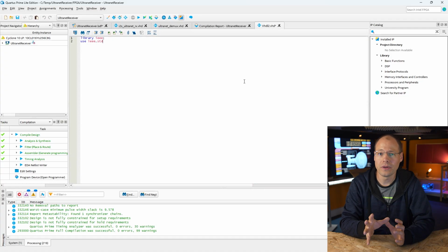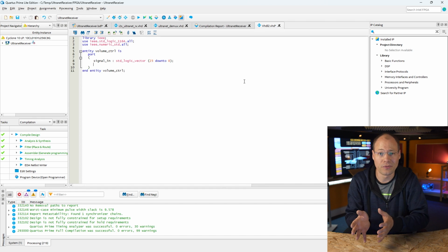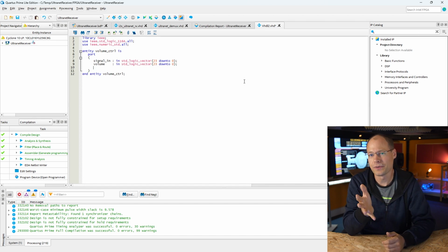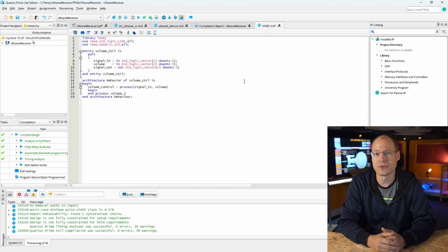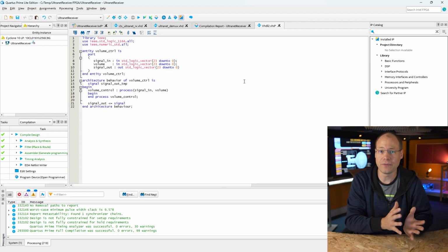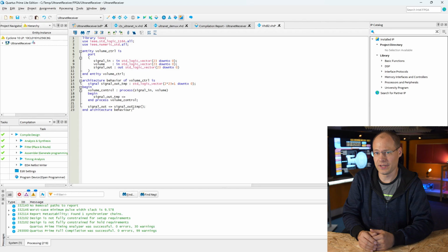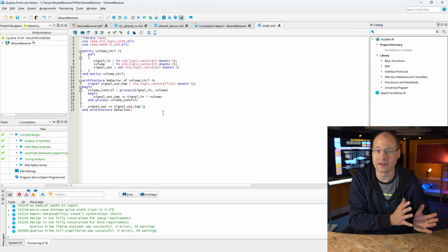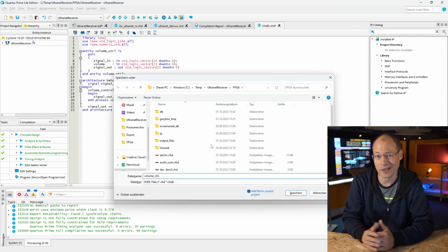For volume control, all we need to do is multiply by a factor between 0 and 1, meaning 0% and 100% volume. Unlike microcontrollers, however, the handling of fractions of a number is a bit more complicated. Therefore, we limit ourselves to a multiplication with a value between 0 and 256, or full 8-bit, and divide the signal by constant 256 by a bit shift of 8 bits to the right. Thus, we can perform the entire calculation with integer values.